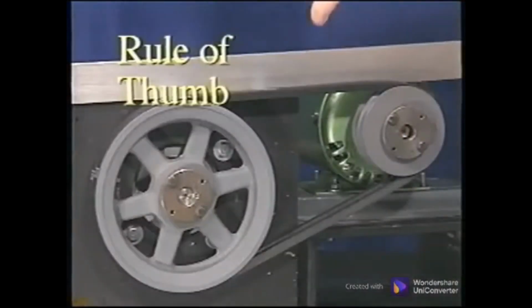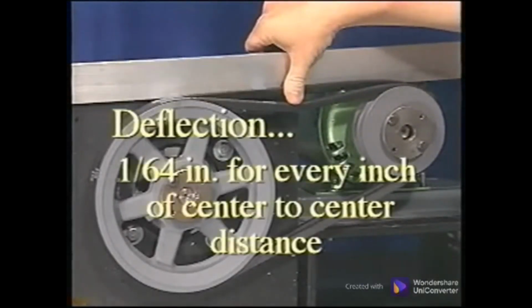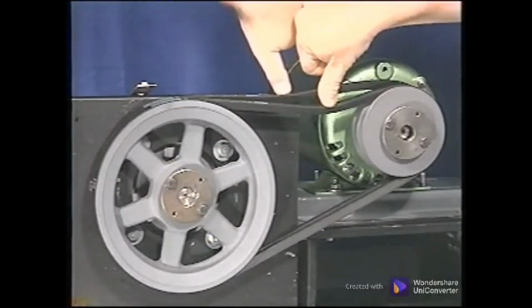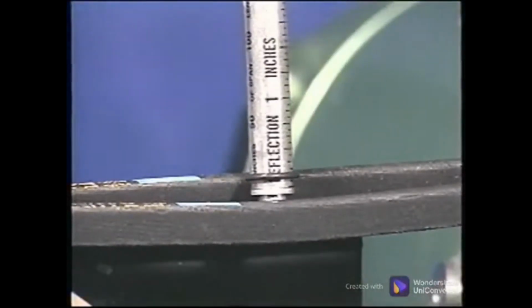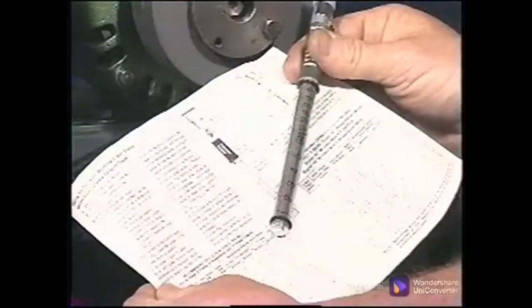The long-standing rule of thumb has been to press on the belt with your thumb and measure the deflection, which should be about 1/64 of an inch for every inch of center to center distance. However, some thumbs are heavyweights and some are featherweights. An improvement on the rule of thumb is a small, inexpensive gauge produced by several belt manufacturers that measures the force applied and has a scale to check the deflection with a given force. Charts provide the recommended force for the various belt types and center-to-center distances.